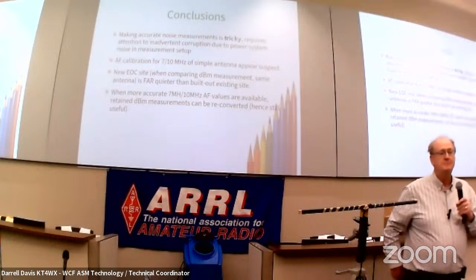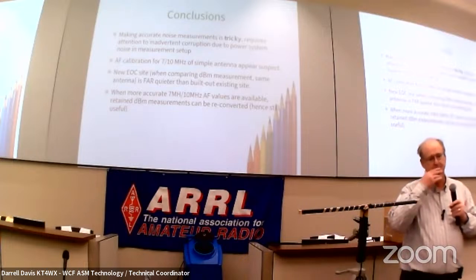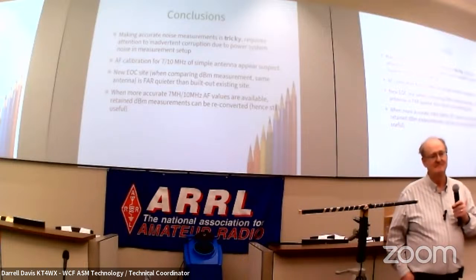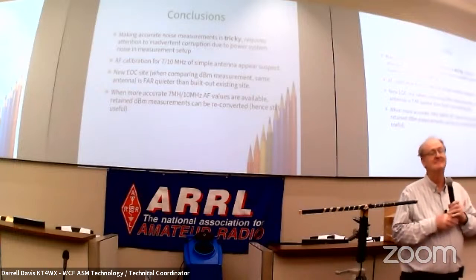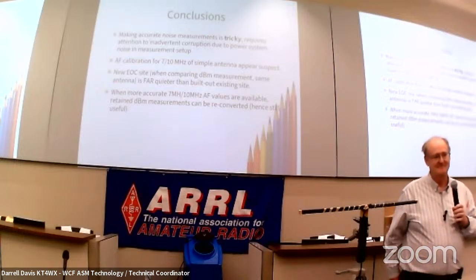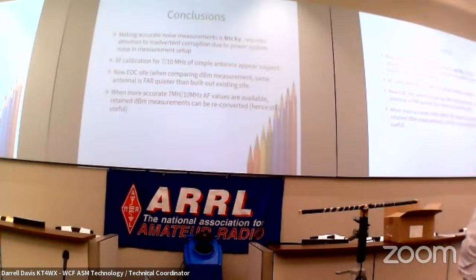One of my students had a light bulb burn out on his truck. So instead of buying an incandescent, he says, hey, I'll buy these long life LEDs. And he told me that whenever he stepped on his brakes, his FM stereo radio quit working. So it was a DC full volt. Yeah, but they have a switching supply built into them, a switching supply inside the bulb to run the LEDs. As small as it was, they did that.